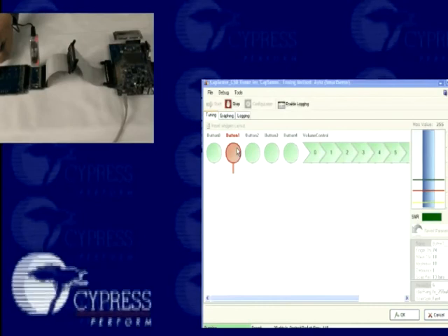As you can see on the screen on the right side, the SNR rate achieved the same level as the demo without the cable. It's 85. This is all thanks to the smart sensing algorithm in PSoC 3 that auto-tunes over 10 parameters without any additional engineering effort. The true value of this solution is system BOM and NRE reduction. The smart sensing algorithm and high immunity to noise ensure CapSense performance over cable. And the fact that zero CPU horsepower is used during CapSense scanning offloads the main central control CPU to perform other system tasks.